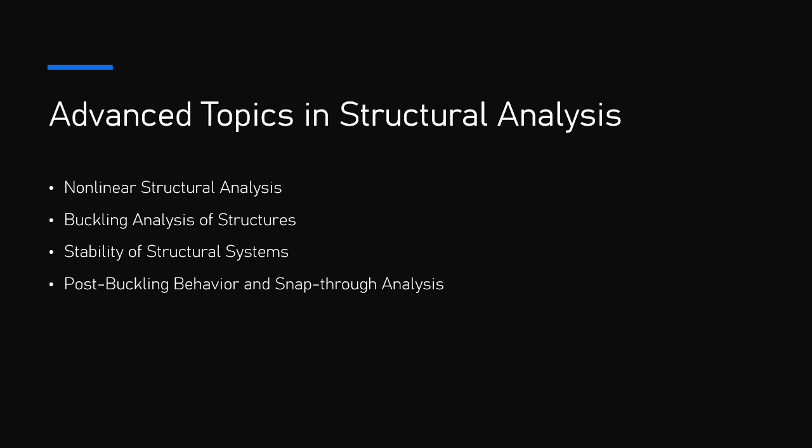3. Tall buildings. Tall buildings are particularly sensitive to lateral stability under wind and seismic loading. Stability analysis for high-rise buildings involves wind-induced sway, the lateral displacement of buildings due to wind forces, and seismic stability, the building's ability to resist and absorb seismic forces, preventing collapse or large deformations. Interaction with foundations. The stability of a building must also consider the interaction with the foundation, particularly in soil structure interaction.